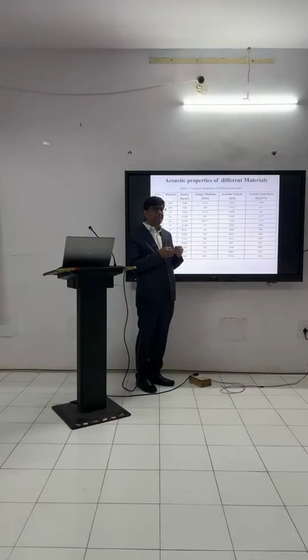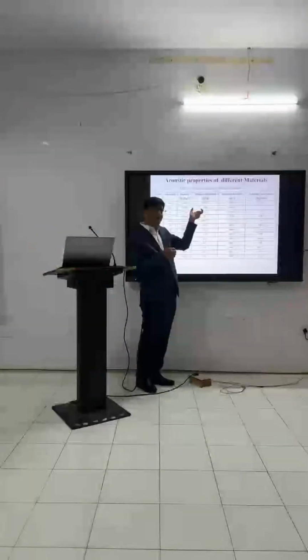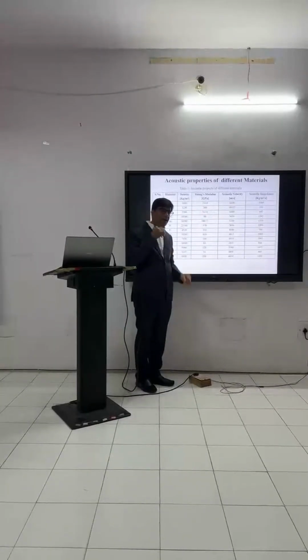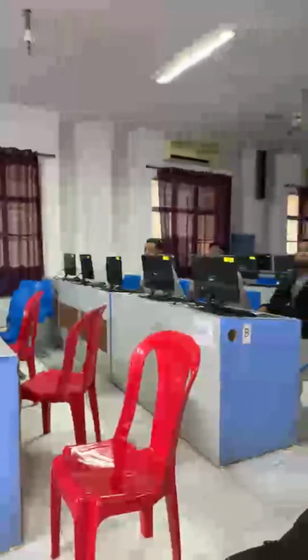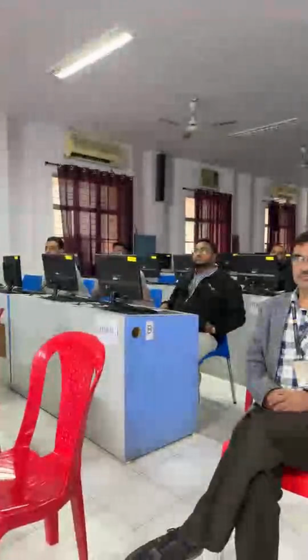This is not very easy to deposit, because in India more than 1,000 to 2,000 people have completed a PhD only in ZnO optimization and ZnO characterization. Very thin film ZnO deposition is easy, but here we require a bulk ZnO layer. Bulk means we require it in microns, 1.5 micron.